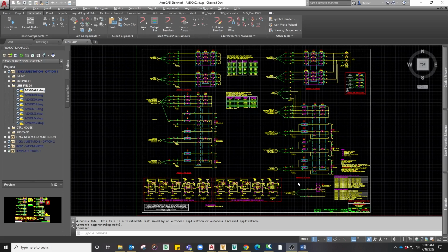In this case, I've created a new standard AC distribution schematic drawing based on its vendor drawing, and I've added that to the main substation project file. I've designed the supplemental standard such that I can copy it out of Vault and add it to any substation design I need for cabling and reporting. The same principle applies to any other standalone panel schematic material that was previously unaccounted for in the schematic diagrams.